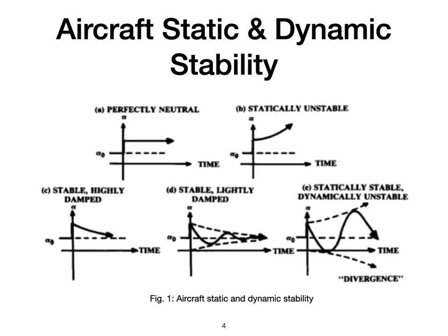Figure E illustrates the restoring forces which are in the right direction, so the aircraft is statically stable. However, the restoring forces are high and damping forces are relatively low. So the aircraft overshoots the original pitch angle by a negative amount, greater than the pitch angle produced by the disturbance.